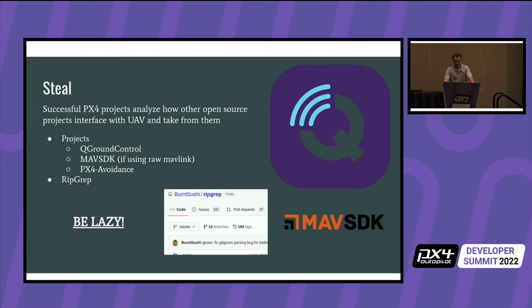When you see something happen in QGroundControl, you can open up the source code and see how they are doing this, such as the do reposition command. How is that being sent over? How are we uploading rally points? So many times I've popped open the source code to QGroundControl and watched what they're doing in there and seen what's going on and said, okay, we can do this on the web interface that we're using, on the onboard computer that's passing around raw MAVLink messages.